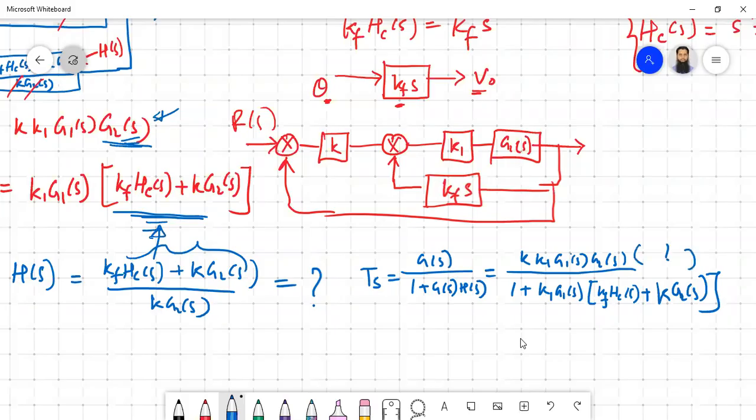Okay, so 0 of your H of S is actually not a 0 of the closed loop. Okay, in the last class, while we were discussing the cascade compensation, if you insert the 0 here, that 0 was actually transmitted here. Okay, so this is the difference with your feedback compensation. So we'll be seeing this phenomenon in detail while we are trying to solve the problem.